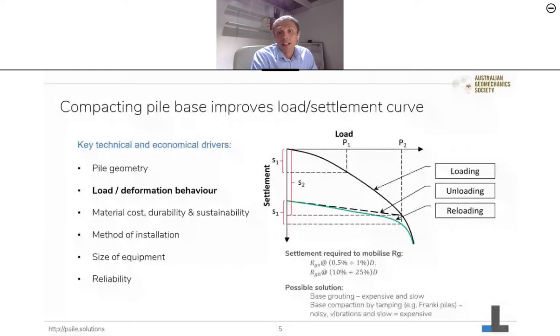required. In case of piles with large diameter bases, this ultimate base capacity may very often not be possible to utilize during the service life of a structure, and that is because it would simply require too much settlement, and that would be detrimental to the structure. So what can be done with that?